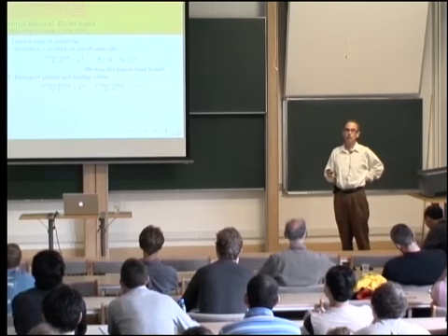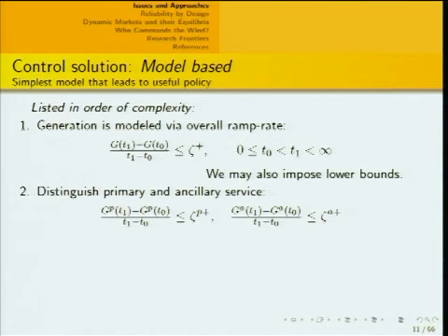Next, I'll look at multiple levels of service. So I might have some generators with one ramp constraint and some with another. These could be, say, nuclear, where this is basically 0, and coal, where it's a bit better. Faster ramping generation is, for example, gas turbine sources. Gas turbine is a more responsive source of generation.